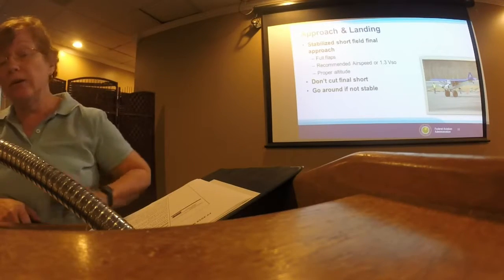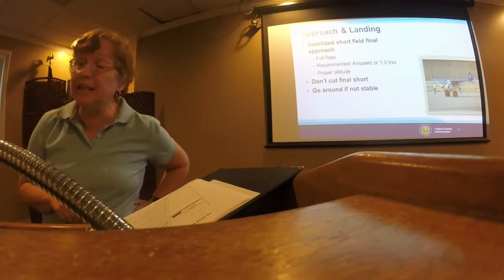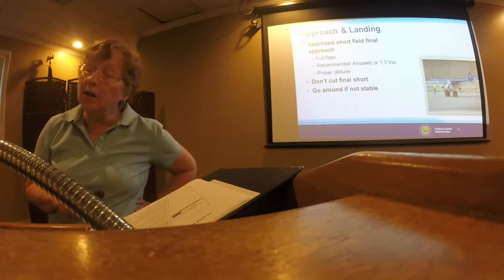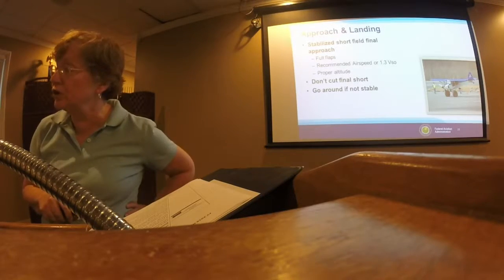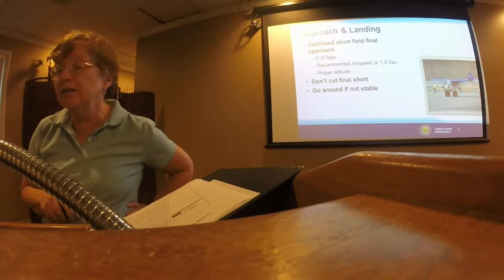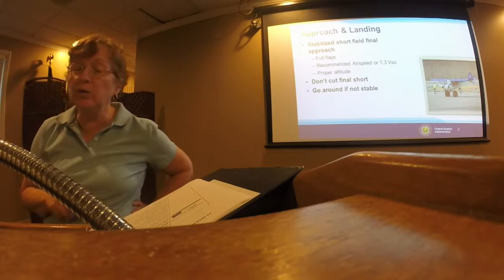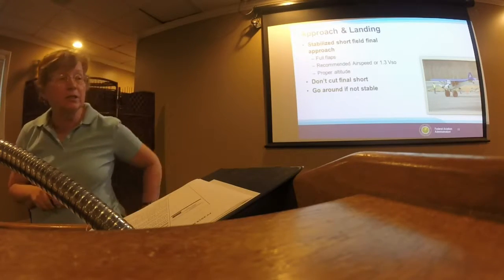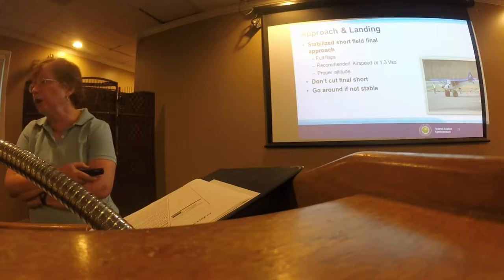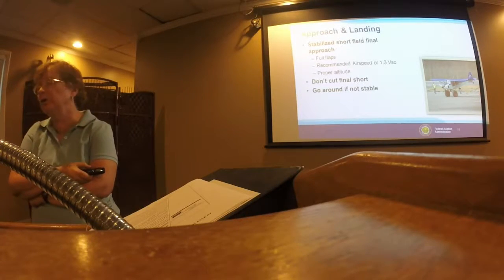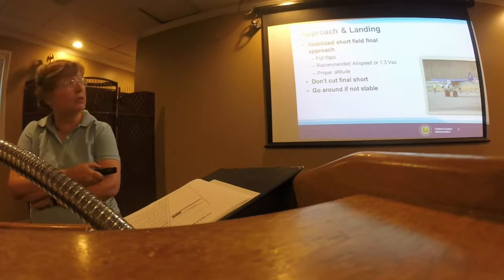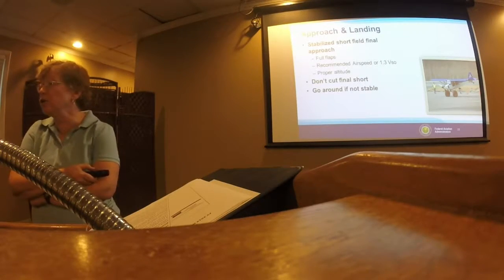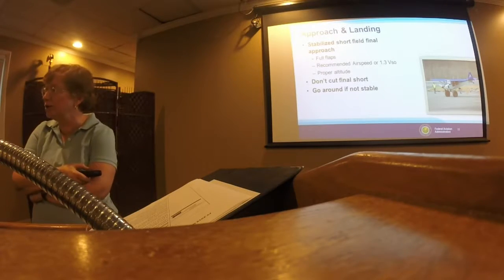All right. Now, when you're landing, the FAA is very much into stabilized approaches. And what they're talking about with this is at some point after you turn final, you should be fully configured. So as much flaps as you're going to put out, the recommended airspeed, or if you don't have a recommended airspeed, which some old planes don't,